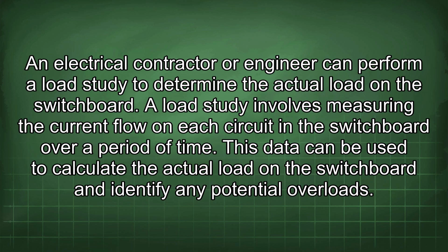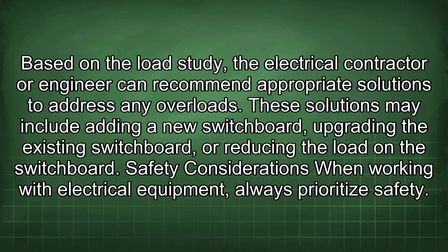An electrical contractor or engineer can perform a load study to determine the actual load on the switchboard. A load study involves measuring the current flow on each circuit in the switchboard over a period of time. This data can be used to calculate the actual load on the switchboard and identify any potential overloads. Based on the load study, the electrical contractor or engineer can recommend appropriate solutions to address any overloads. These solutions may include adding a new switchboard, upgrading the existing switchboard, or reducing the load on the switchboard.